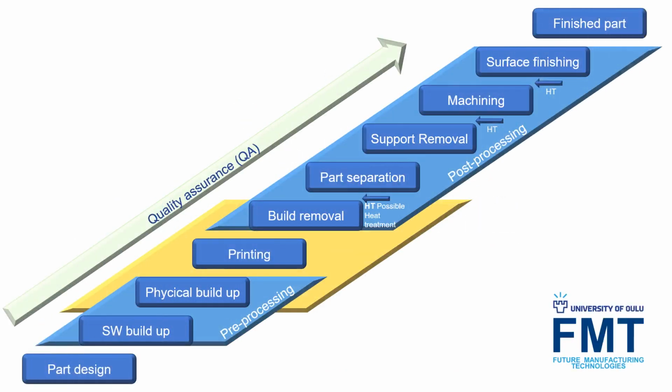As a brief summary, it could be noted that the technical requirements, design and work planning of a part greatly influence the need for post-processing of the part. The part should be designed so that the need for post-processing is kept to a minimum. It is also good to be aware of what post-treatment possibilities are in use. In practice, this means that the shape is designed to minimize the need for support structures. If the part has exact features that require machining, the attachment of the part during machining should be considered at the design stage. If possible, the overall tolerance for surface roughness should be kept high.